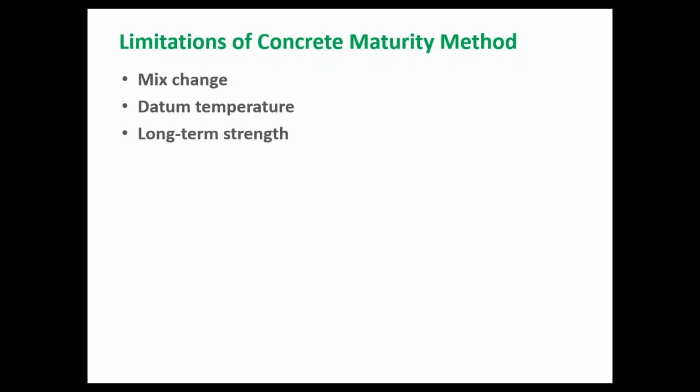Maturity is not designed for long-term strength monitoring. So it's not replacing the 28-day strengths. You still have to do the standard cured cylinders. And if you are interested in knowing the strengths of concrete more than, I would say, 14 days, you need to break cylinders. Maturity is designed and developed for earliest stage strength development, where you're dealing with formwork removal, post-tensioning, or things like that during the first week or so.